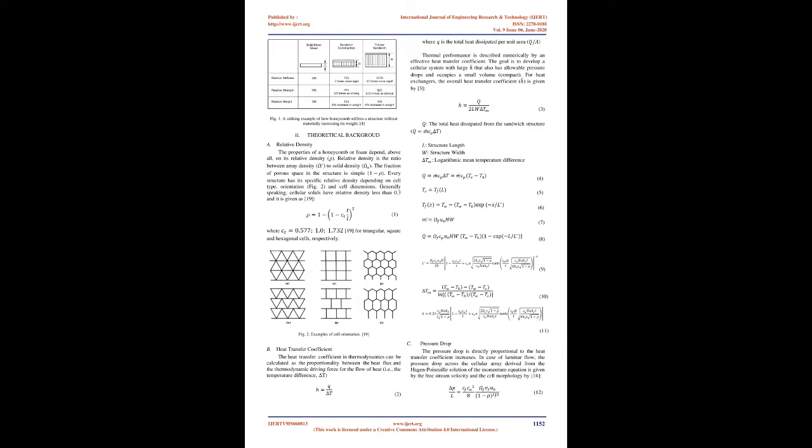Layered metals are additionally a type of intermittent cell metal structure. They have their voids organized one way, enabling fluid flow in one direction, but not in other directions. They are broadly used in buildings, in transport construction, and for cross-flow heat exchangers. Recently, significant interest has risen in cross-section structures which have three-dimensional interconnected void spaces suitable for allowing fluid to flow through them. The structures to be optimized are composed of similar unit cells with dimensions ranging from tens of micrometers to tens of millimeters.